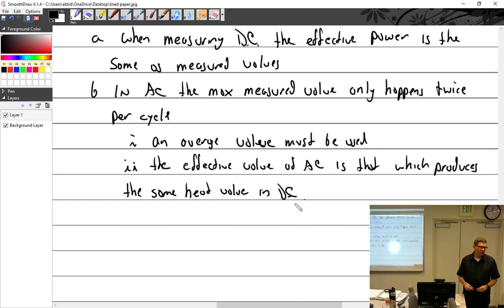So you have 1.2 volts and 6 amps, and so you roughly have 6 watts of power through there. So they take it apart and then they get an AC generator and they have to turn up the AC until they get the same heat. Okay, measures the same now. And so, what do you got over on the scope? And, wow, we're doing a lot more than 1.2 volts. We're up at 1.4 times that. So, okay, well, there we go. That's the same then. So that power is that power.